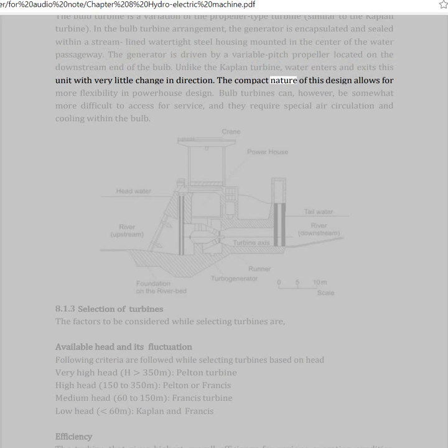The compact nature of this design allows for more flexibility in powerhouse design. Bulb turbines can, however, be somewhat more difficult to access for service, and they require special air circulation and cooling within the bulb.